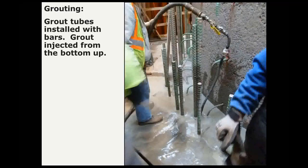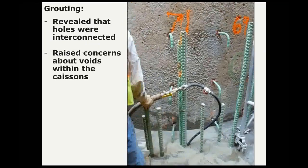And as part of that grouting operation, we uncovered another unpleasant surprise: we discovered that we were putting more grout in the holes than there was hole to put grout in. And sometimes when we grouted one hole, the hole next to it would also fill with grout. So this indicated that there were voids somewhere in the caisson that were interconnecting the holes, and that raised some questions about both the validity of our analysis and the capacity of the caissons.